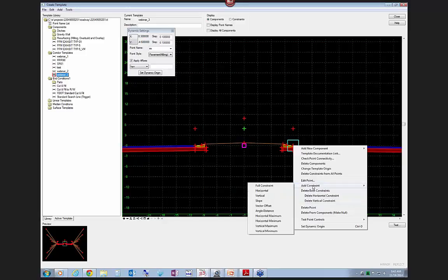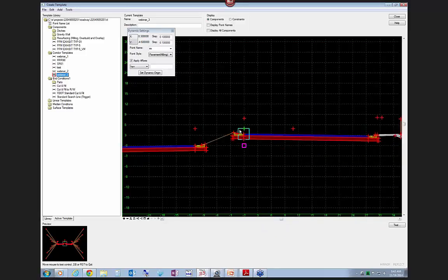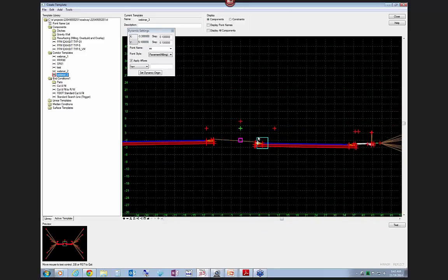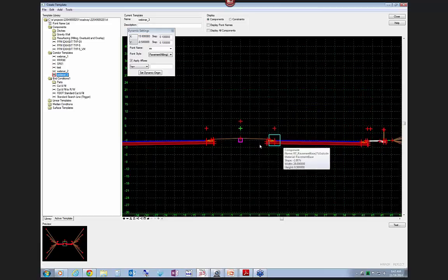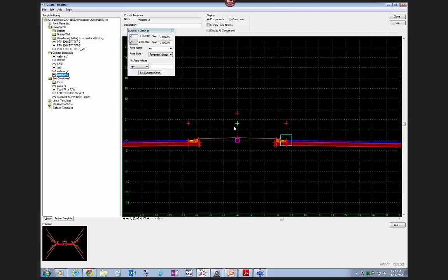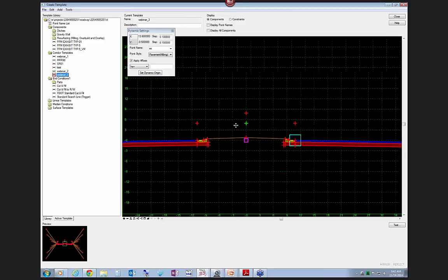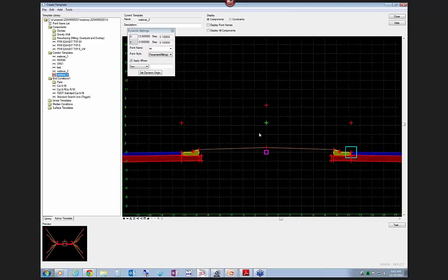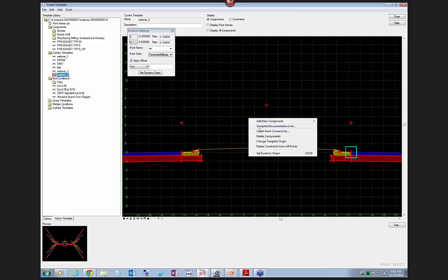So if I did a test, and I did a test all, notice that this whole roadway side changes. And what I'm really wanting to do is add an additional lane width in the median for a left turn or for a traffic separator. I also don't have a crossover situation in here, so when I get to an intersection, it's going to try to draw a curve right through the middle of it, and obviously that's not anything that you want to model. So the first thing I'll do is delete out this static median,